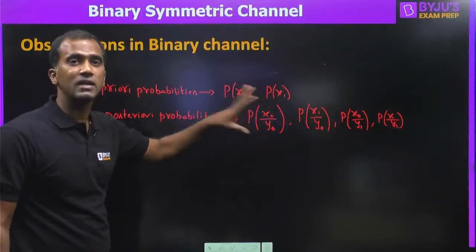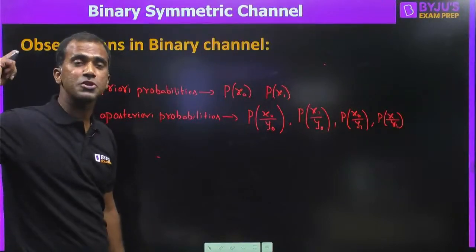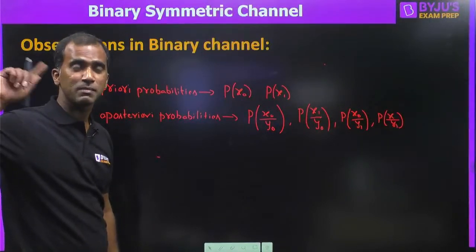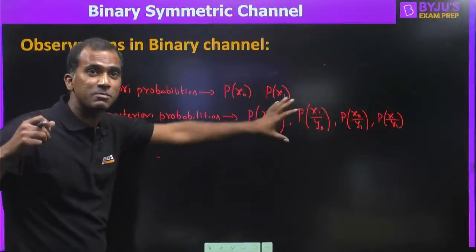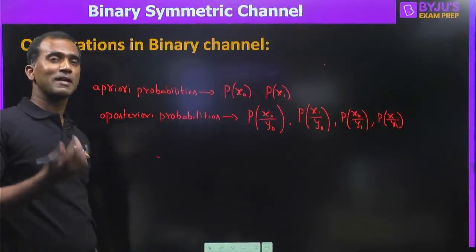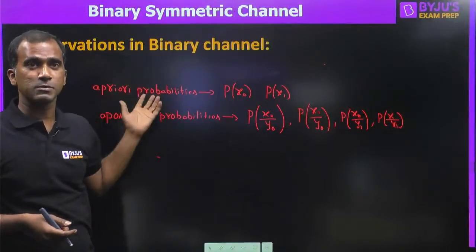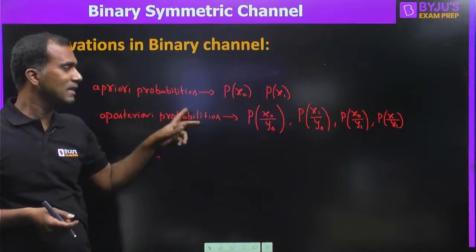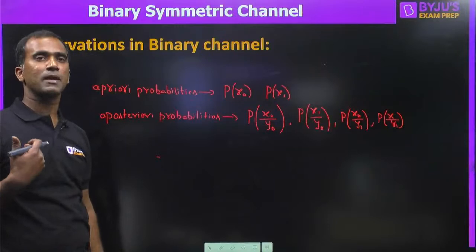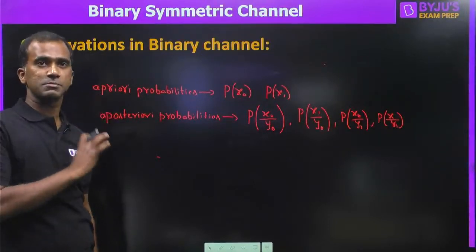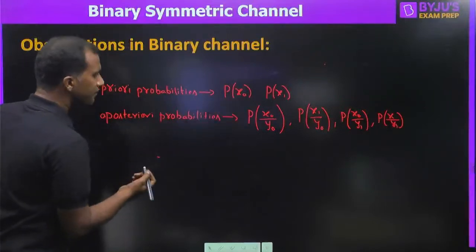But these are not readily available. MAP talks about the maximum a posteriori probability criteria, which means the MAP criteria is based on these probabilities. So we will first write the MAP criteria based on these probabilities. But the probabilities available to us are y given x probabilities. But we know there is a link between these two. Using that link, we can get the MAP criteria relation in terms of y given x probabilities. That is possible, right? So first of all, let us understand this.